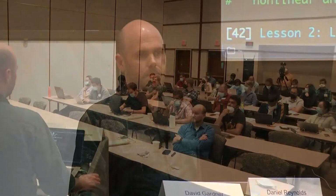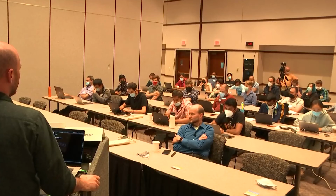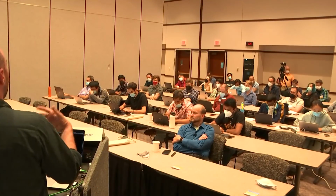And if it's really nonlinear, does it use a finite difference approximation of the Jacobian? It depends on what the linear solver is. Because we're doing this parallel PDE case, it's going to do a Newton-Krylov scheme, so it's going to use a Krylov solver for the linear solver specifically. It's using GMRES, and it is doing a finite difference approximation of the Jacobian vector product. So it's not actually forming the matrix, which in this case would be a banded system. It's just approximating that with